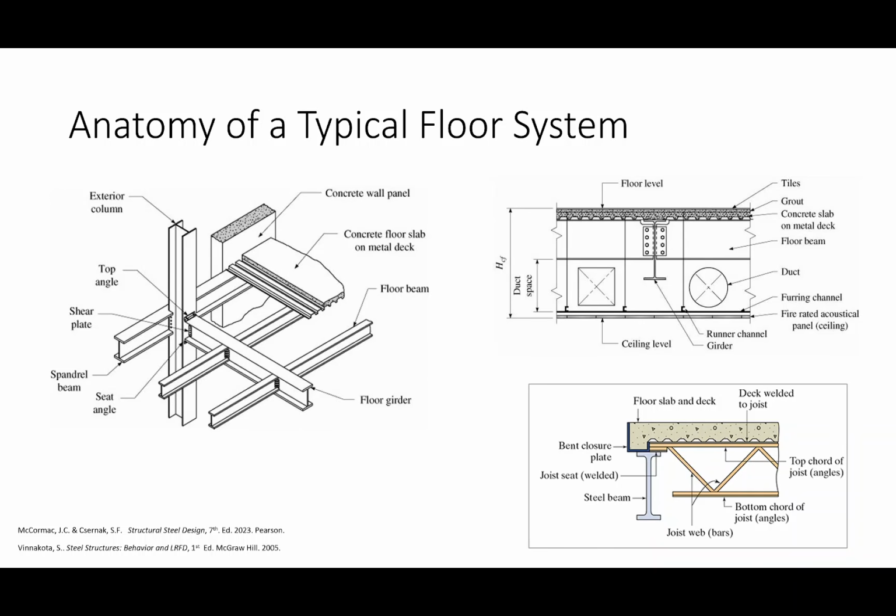So I have to provide a floor beam that's strong enough to support all these loads. So, an architectural constraint, I have to fit that floor beam in here. It can't be deeper, right? Because the architect said this is how much room you've got, okay? So this is an architectural constraint that we would need to operate under for the purposes of design, okay?